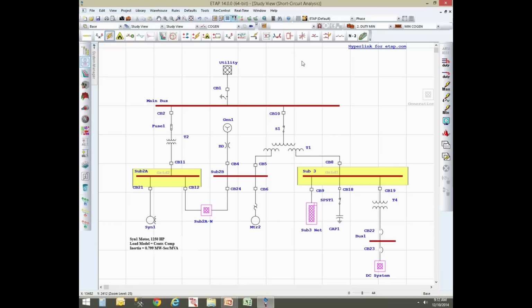And for this example here, I've done 3 configurations. I'm basically considering cogeneration, which is as you see right now on the screen, utility with my generator in service. I've also configured an emergency configuration, in the case that I'm just energizing the system with my in-house generator, and then normal operation if I'm just operating the facility with the utility incoming.